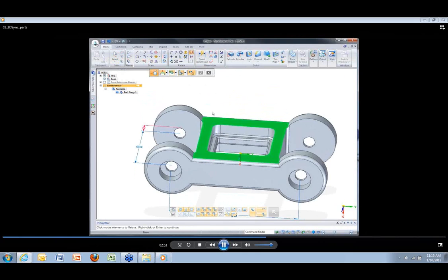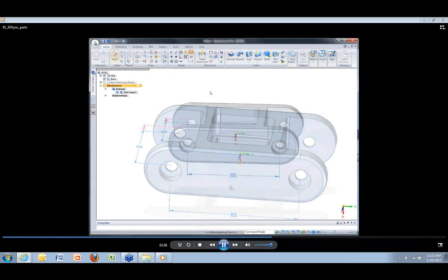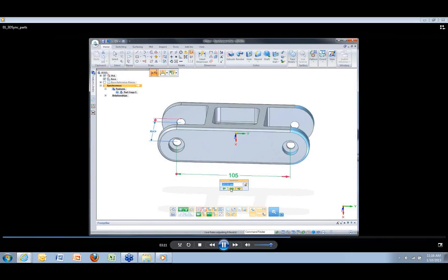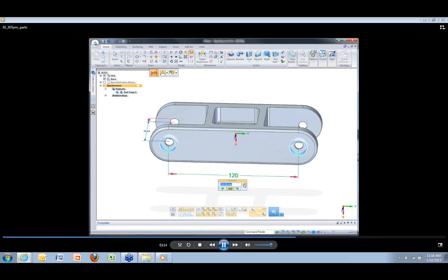To complement dimensional edits, geometric relationships such as this tangency condition can be added. Live rules automatically find symmetry within the part and apply tangency to the bottom face chain. Within 3D driving dimensions, the direction of the edit can be managed: left, right, or symmetric. During each edit, notice how Live Rules automatically keeps holes aligned and concentric.